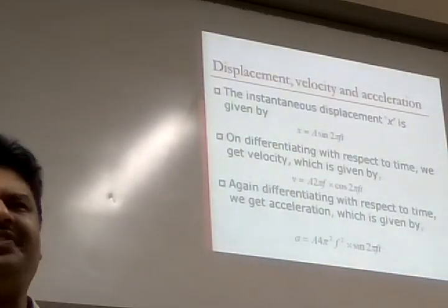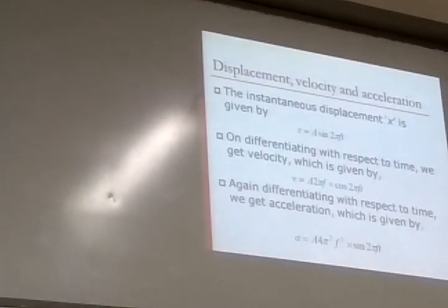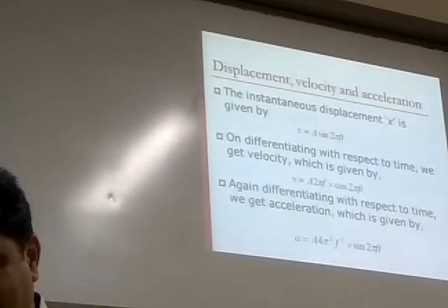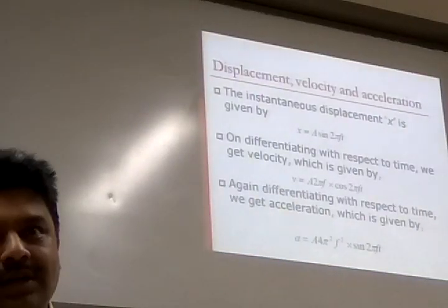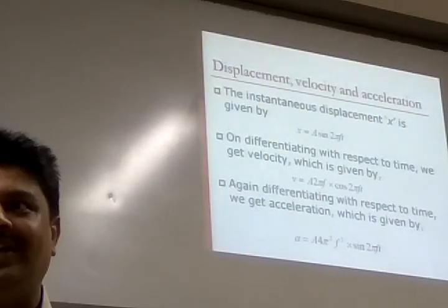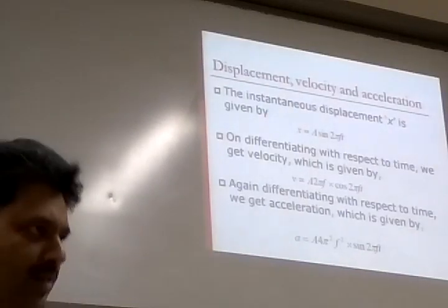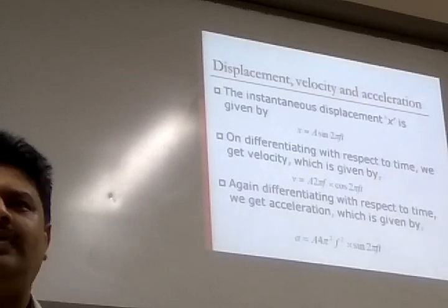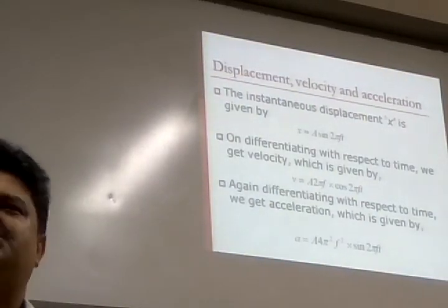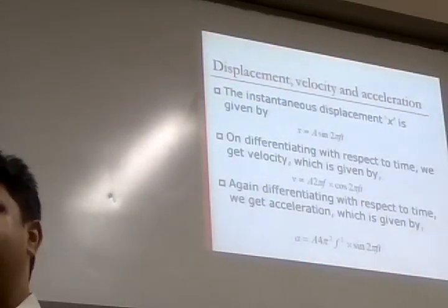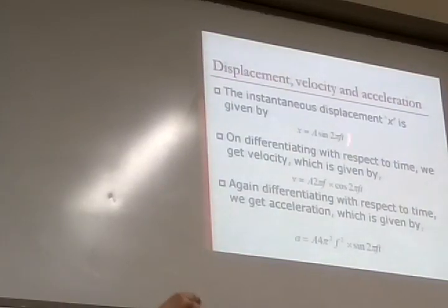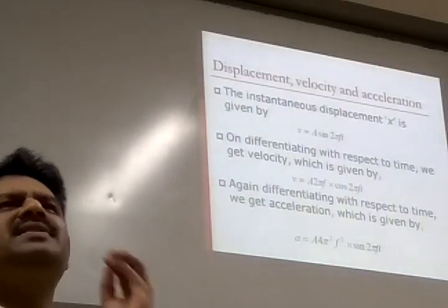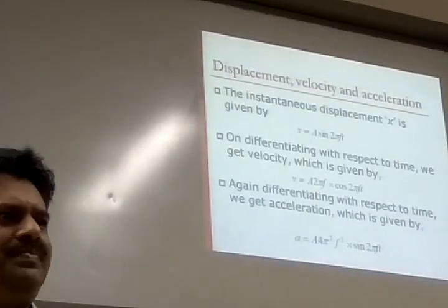If the range of frequency is very low, for example seismic displacement, an earthquake, or a movement of bigger stones under the earth, some sound will come actually, a tsunami, or landsliding, those are very low frequency and will move slowly. The frequency will be 1 hertz to 5 hertz. Those movements are better captured with displacement. For medium frequencies, velocity: slow speed, 60 rpm, 50 rpm.